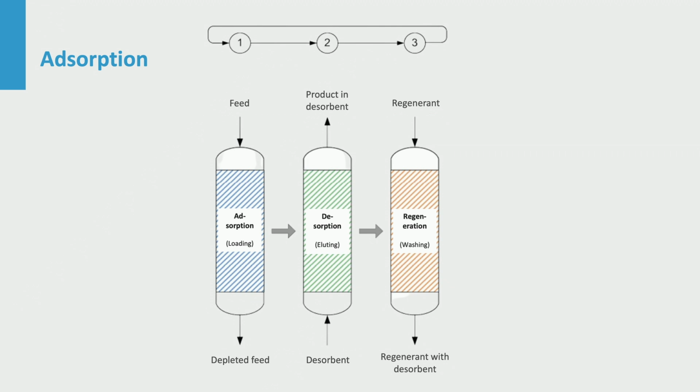After adsorption has saturated the column to its end, you also need desorption and regeneration to bring the sorbent back to its original condition. Sorbent material is too valuable for single use. Desorption and regeneration lead to side streams that are easily forgotten in early design stages. Products still must be separated from the desorbent in an additional operation.